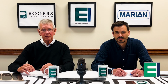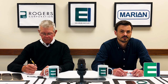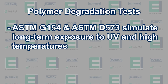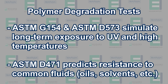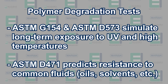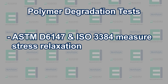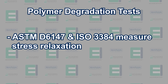There are a few tests that can be used to build these expectations and to be able to compare materials when tested and when results are published. The ASTM tests G154 and D573 simulate long-term outdoor exposure to UV and exposure to elevated temperatures. ASTM D471 is a test that predicts how a material will resist common fluids like oils and solvents. For measuring stress relaxation, that is, measuring the loss of sealing force over time under constant compression, ASTM D6147 and the ISO test 3384 are good predictors.